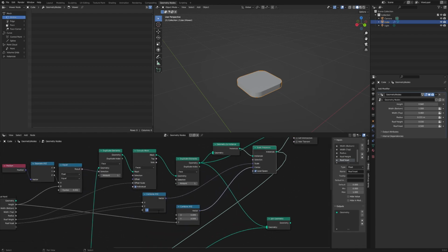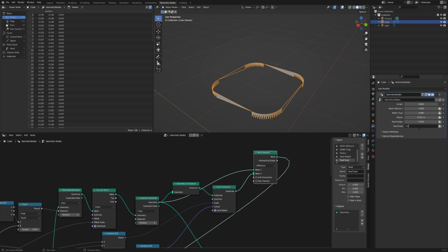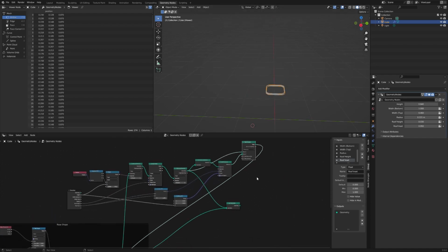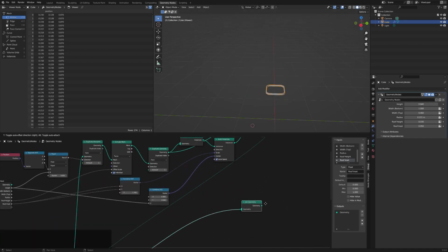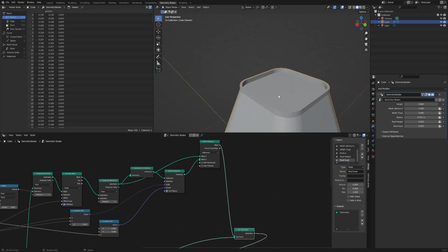So what we want to do is increase the height of the thing we're cutting out, so that the calculator is a little bit more efficient. If you treat it as perfectly the same size, it struggles sometimes. Now you get a really nice idea: if I have an inset of 1, it really breaks because it tries subtracting basically itself from itself. But if you do it as 0.95, for example, you get a really small roof kind of inset on the top. And then rather than having that piece of the roof come into the join geometry, let's have that. So now we have this nice little detail on top.